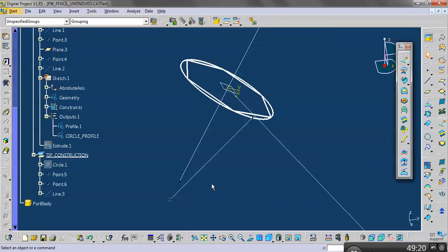Now we can revolve. Does everybody have the line? Revolve is under translate. No, it's not. Revolve is under extrude. Yes, it is. So there's the extrude button over here. Yours is probably docked on the toolbar somewhere. Click the little black down arrow button, and there's revolve. So revolve is hidden under extrude. Press revolve.